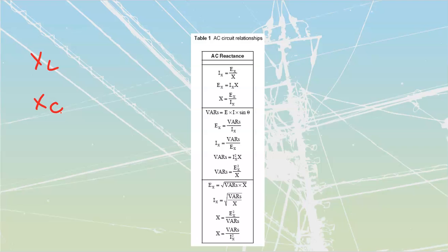For the rest, you're really just seeing a repetition of that same third column that we had, where it was the reactance. And the reactance column, once again, does not have any sort of subscripting to it. It just says X. It's up to you to determine whether a circuit is going to be inductive or capacitive. For this learning test, they're all capacitive. And then once you know what that is, go and apply the proper component to it.